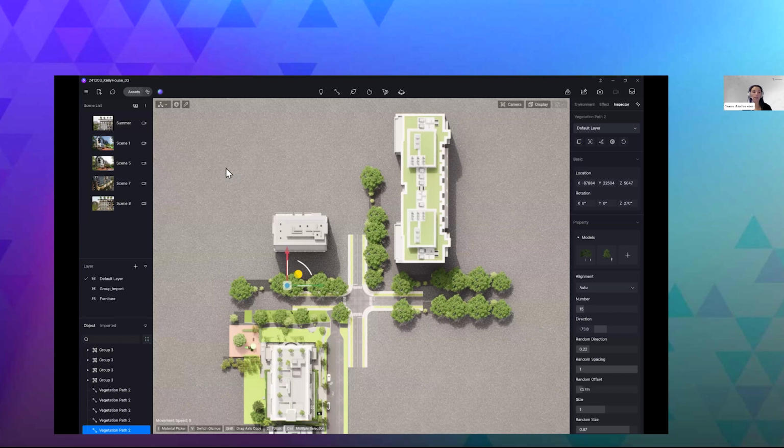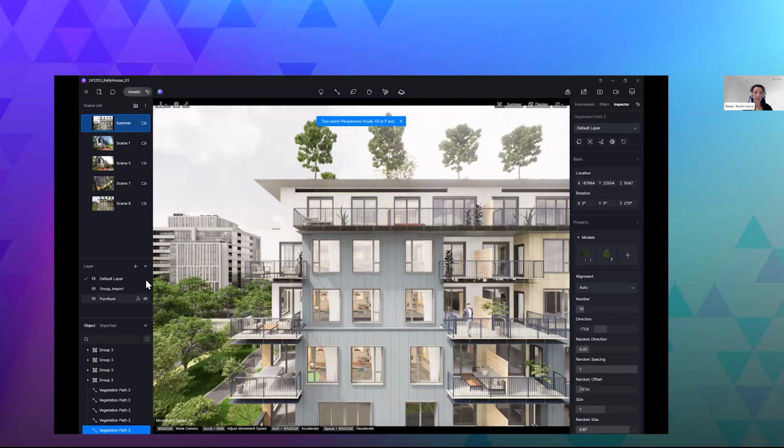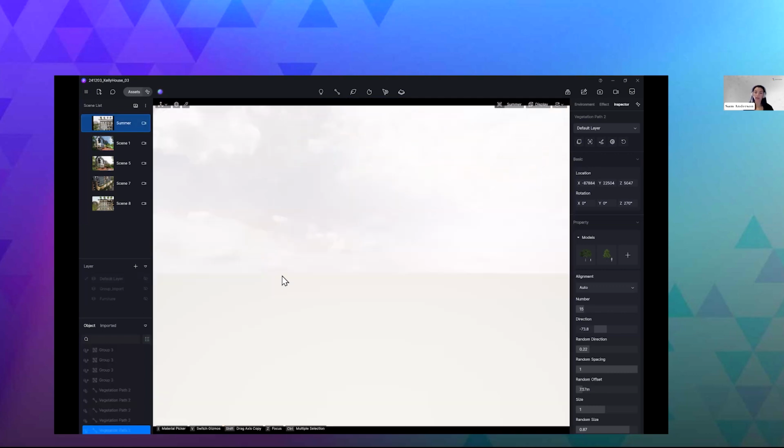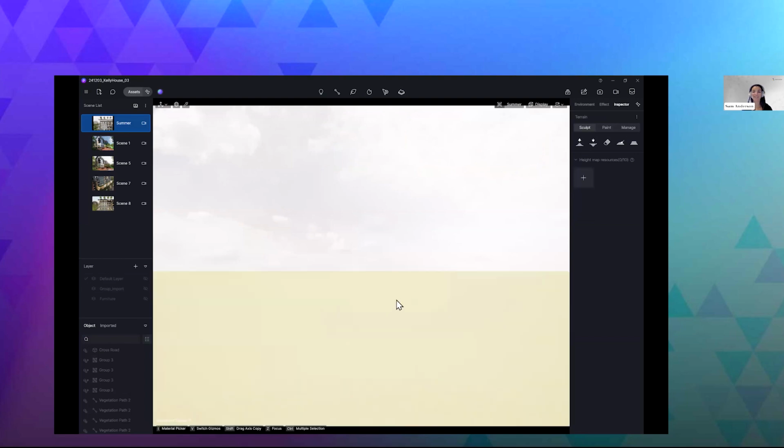So in order to do that, I'll just go back up to my scene. And I'm actually going to hide some of these elements so that I can quickly build out terrain. So here I have hidden all of my geometry, and I'm going to go up to the top toolbar, go over to the right-hand side, and there is a terrain icon here. When I select this, it is automatically going to pop in a grass plane into the scene. And on the right-hand side, you'll get all of the different tools in order to work with that landscape.